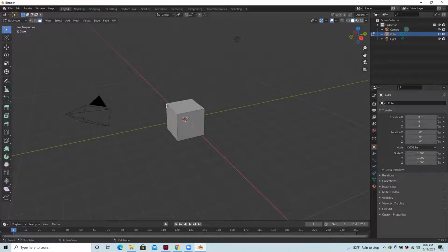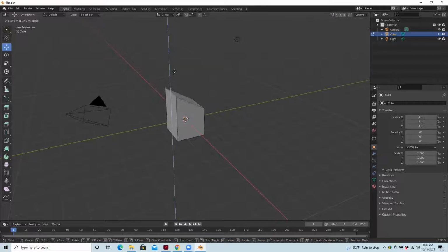I'd actually like to pull one of the intersections of two faces. So I'm going to switch to edge select, and then I'm going to try to click on the line in between the edge. It looks like it's selected, it's highlighted. And then once it's selected, I can switch to other tools. Like I'm going to switch to move, and I think I'll pull that straight up.